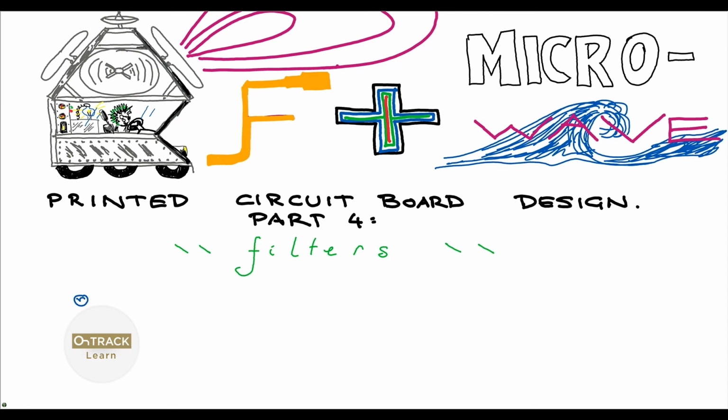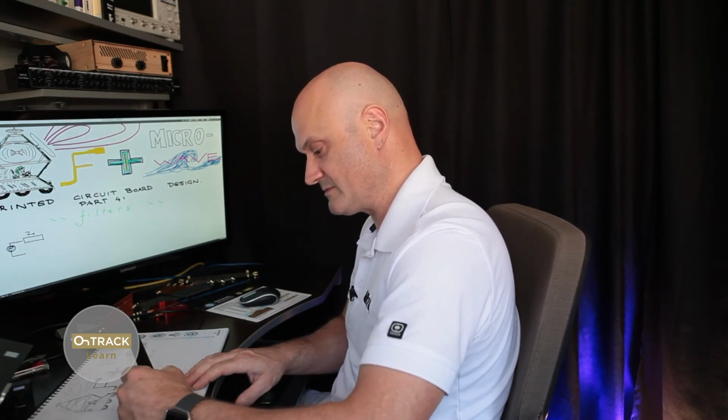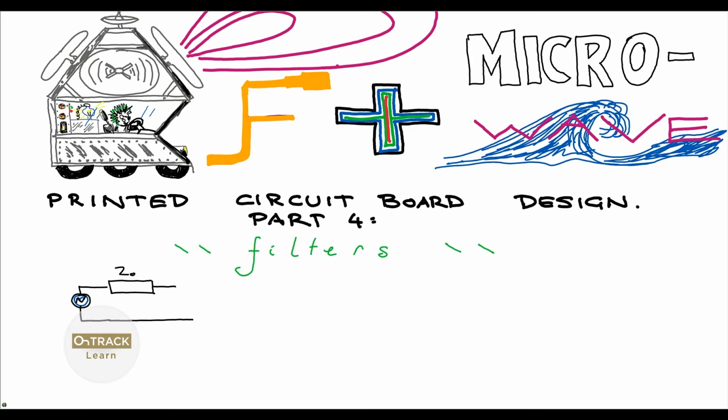Let's say we have some kind of source coming in. We have our system impedance, Z0, and some transmission line segment. And if we have another segment going to ground like this, down the line, and this is all Z0, then if this segment here is a quarter wavelength, then at the resonant frequency of our system, the center frequency where that is 1/4 wavelength, this short circuit actually appears like an open, as you recall.